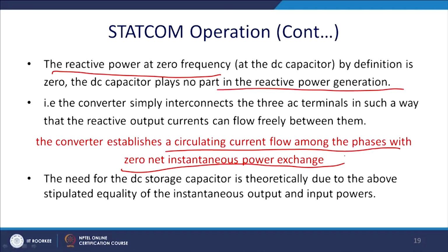So, this is one of the major features of the Statcom, and thus it handles a very low amount of real power. That real power is just to meet the losses. So, for this reason the need for a DC storage is theoretically not required, due to the above stipulated equality of instantaneous output and input powers.